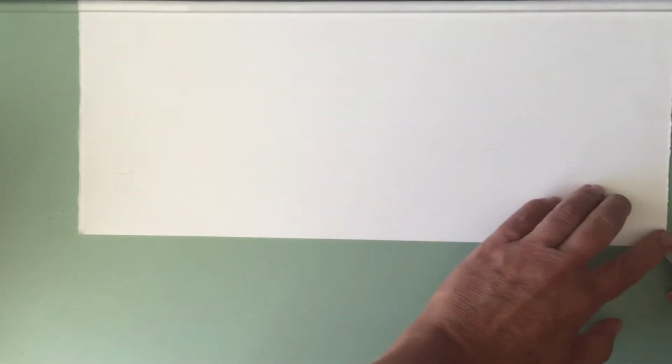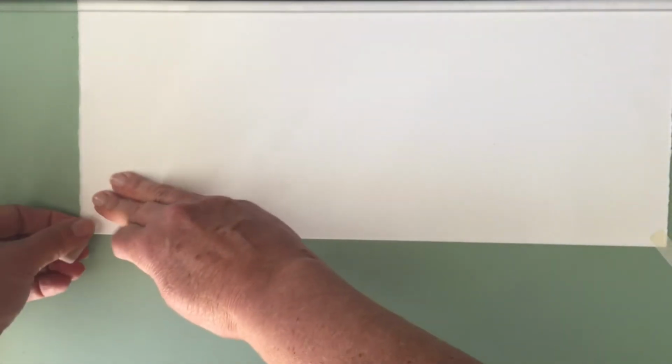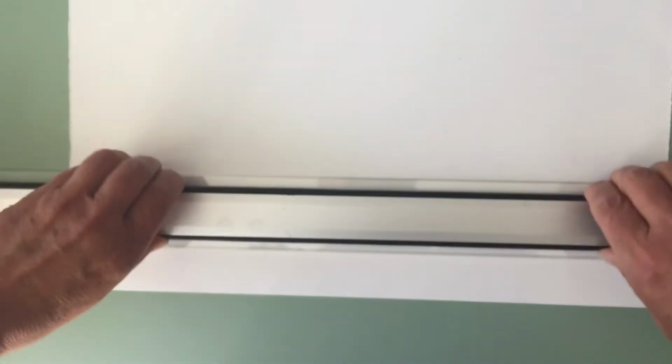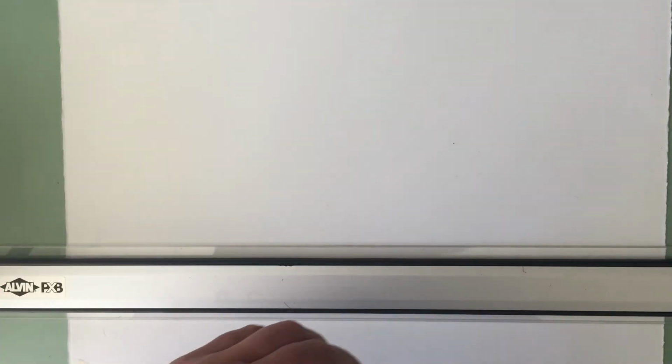And you see when I move it, I lift it. I never drag it across the work surface, because if there's any dust or any graphite left over on there, it'll smear on the paper, and you really don't want that to happen. And if you start off methodical, because you will get some muck and grime over there, it sort of gives you a little peace of mind, a sense of stillness, and then you can draw more effectively. So there, we're all taped down, and taping away from myself, and I'm going to move my parallel rule down here. So as we said, we're going to learn how to draw some lines.